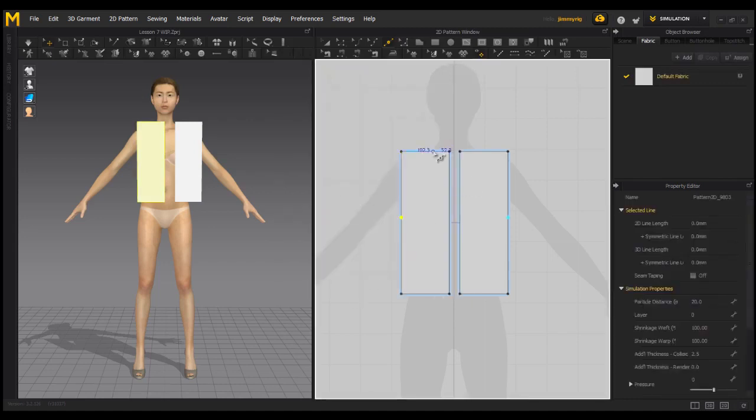Next we are going to add a point here, and this one is for the neck. You can see that while we have symmetrization on, we don't even have to worry about the other side because everything is done automatically for us. So this makes our work a lot easier. My suggestion is, as soon as you mirror copy the other side, immediately apply symmetrization afterward.